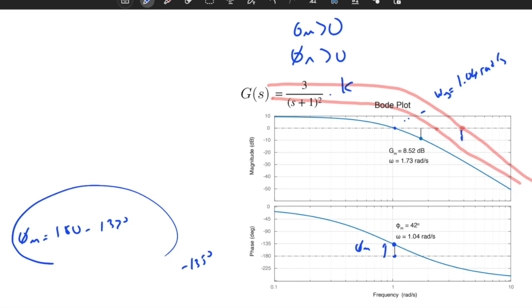If I look at the phase, I'm just increasing the gain, adding a gain to the system. As you can see, it now crosses a phase of approximately minus 225 degrees. If I compute the phase margin, it will have a different direction. This direction is not preserved, so my phase margin is now equal to minus 45 degrees, which is a negative phase margin. Negative phase margin means that the system is unstable.